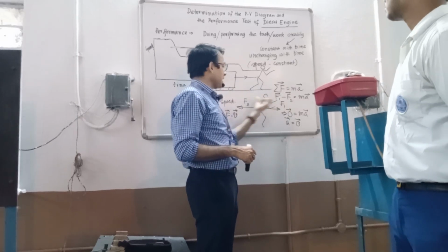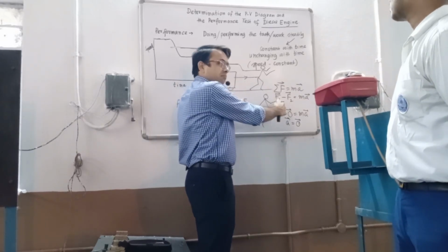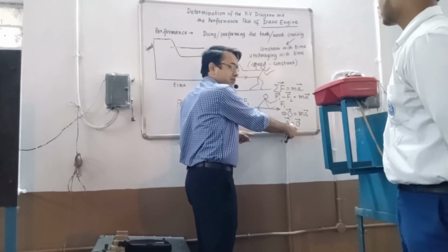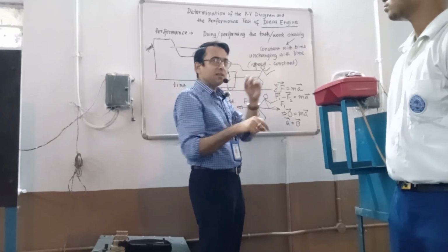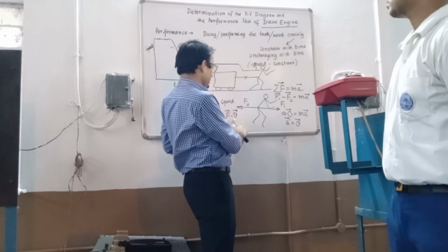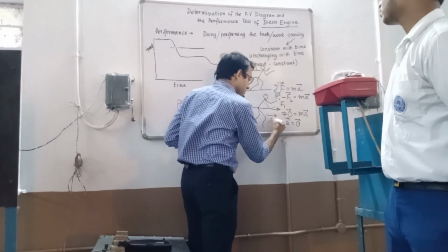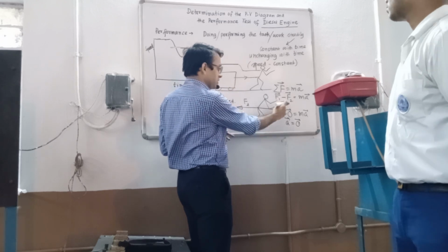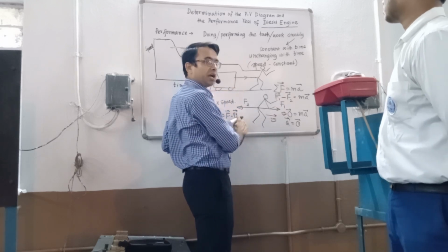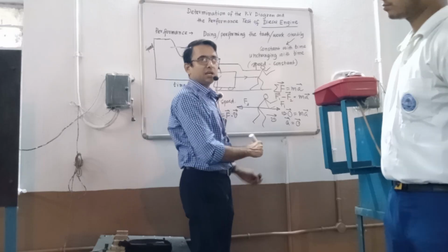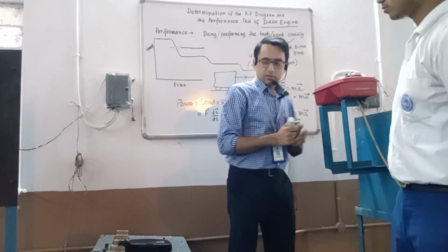By applying this, I can understand that they must be the same, because the speed is constant, and then I can calculate the power. Force multiplied by velocity: I can measure the velocity, I can measure the force, therefore I can get the power. That is the idea of the performance test. Okay, clear?